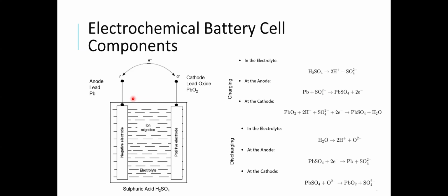So again, lead acid batteries are tolerant to overcharge up to a point, and if I'm overcharging the battery, I need to do it at a relatively slow rate so that this hydrogen doesn't build up and there's time for the hydrogen to break up again and instead just make water as shown here.